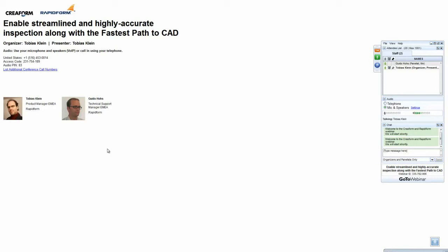Can we use this software to obtain the surface roughness of the object scanned? If your scanner is capable of capturing the surface roughness in the desired accuracy, then you could use, for example, the color deviation mapping and the tolerance to see where your roughness is out of tolerance or in tolerance. This is possible, yes. However, your scanner or point acquiring device has to have an accuracy which is inside your roughness.